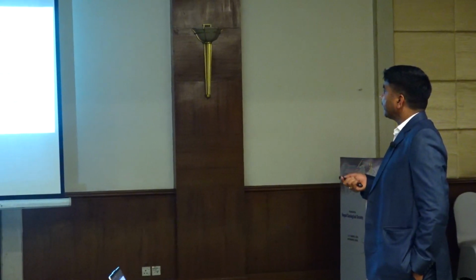So this is the underground excavation cycle. What we have started from drilling, then charging up blasting material, then blasting and ventilation, mucking, scaling, and ground support system and surveying mapping. So drilling and blasting is most common where various size of drilling is required. But in drilling and blasting, there is always associated with unavoidable negative effect, that is ground vibration, overbreak or backbreak, noise and fire.